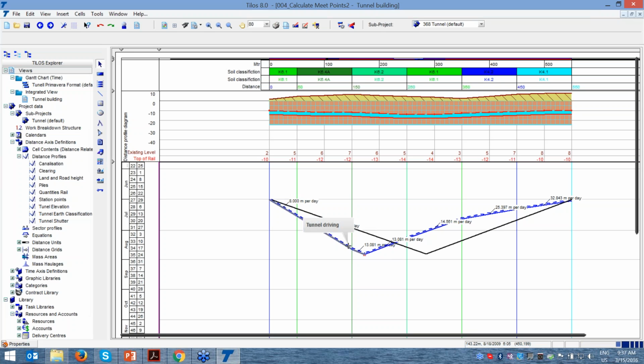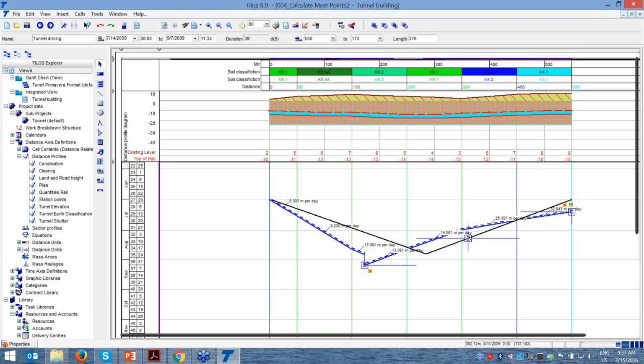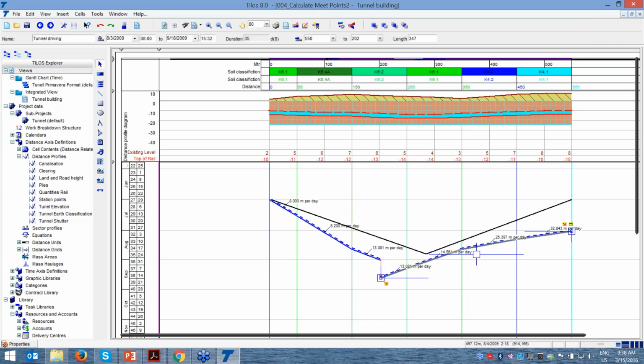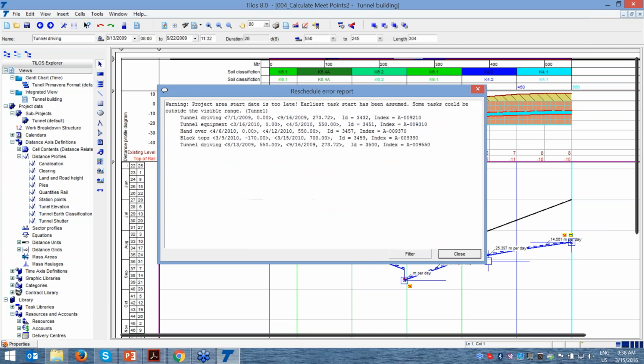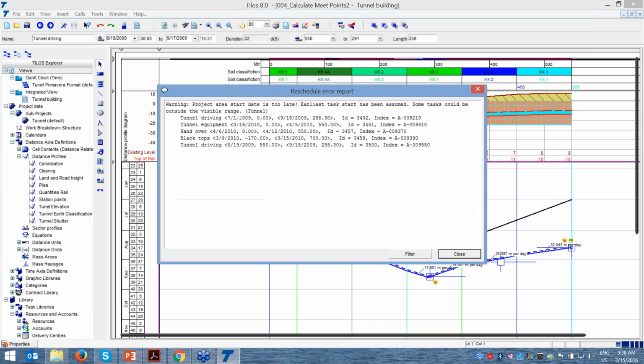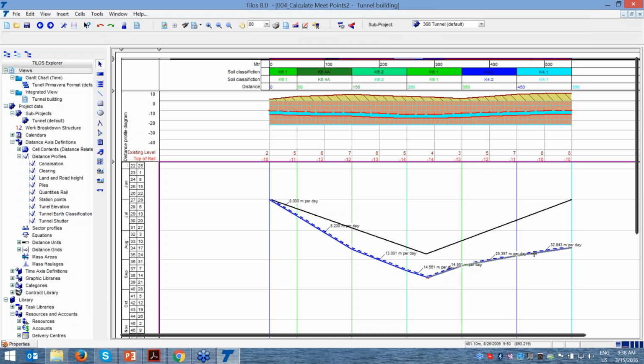It means that, okay, we want them to meet here, so I have a luxury. I can say that TBM2 starts a bit later. Why am I starting earlier? Now I calculate again, and it comes to the left side, which is in the middle. A little bit more, I am just starting in August for TBM2. And you can see that the meeting point is coming left. A little bit also start later. As you see, I am doing what-if analysis, like drawing something. Even if I'm not a planner, I can just find out, okay, this is what we want.